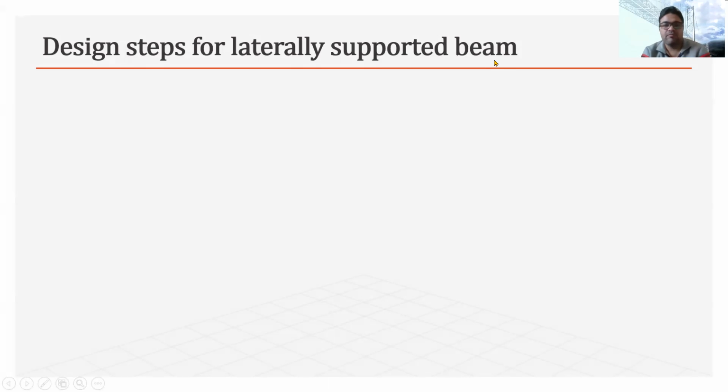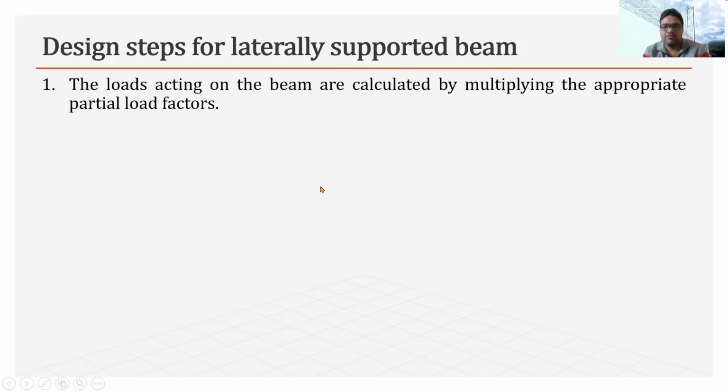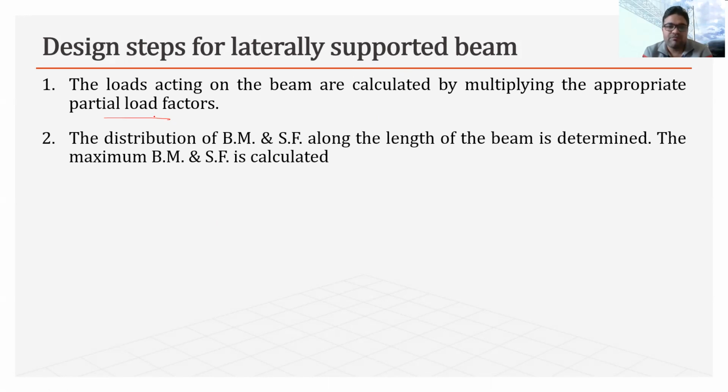Hello, welcome back. In this part, we will discuss the design steps that we will follow to design the laterally supported beam. In the first step, first of all, we will calculate the loads acting on the beam, and we will apply the appropriate partial load factor so that we can find them as a factored load. And after that, we will find out the factored bending moment and shear force along the length of the beam, and then